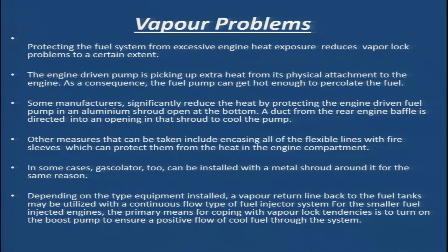Since the engine driven fuel pump is mounted on the engine accessory pad, because of its physical attachment and its surroundings, the engine driven fuel pump will also absorb some heat, and as a result the fuel pump gets hot enough that it helps in vapor formation.